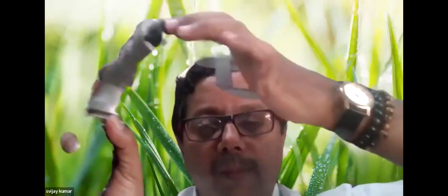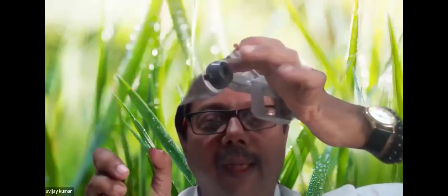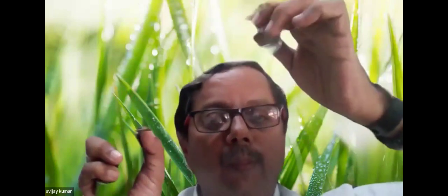The nozzles are all openable. Every nozzle can be opened with the help of a spanner, and it can be cleaned and put back. So maintenance is actually very minimum. And if the water source is like a river or a tank, around the foot well you put in a wire basket so that big chunks of algae or other moss will not enter. And then the water is pumped into the system.